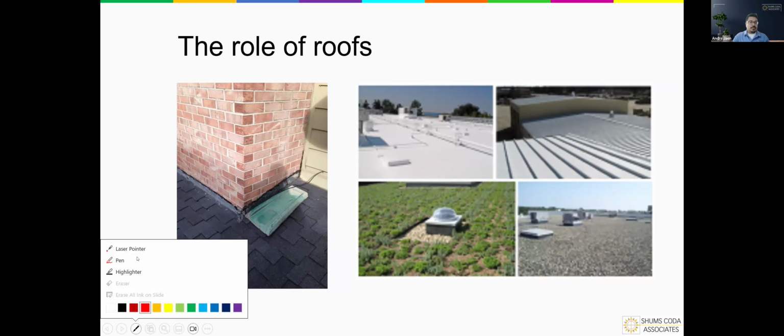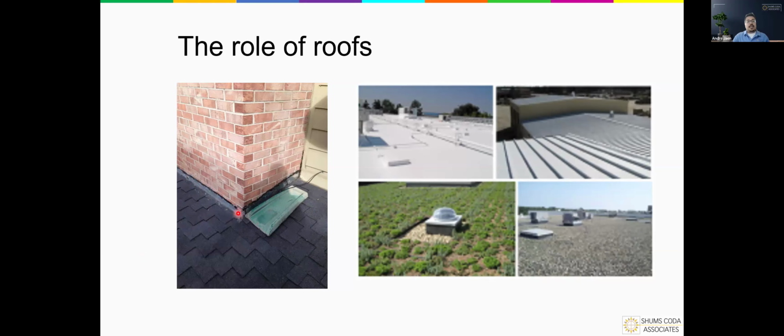Let me turn on the little laser pointer so it's just easy to see. That leading edge of that shingle would be running parallel to the wall structure over here. And so that's where you'd see head wall flashing and, again, counter flashing. So there are right and wrong ways to definitely go about roofing in this, but it's also a consideration again